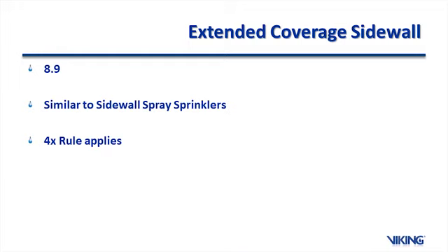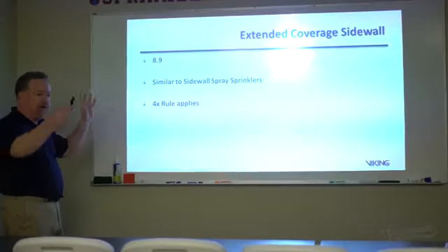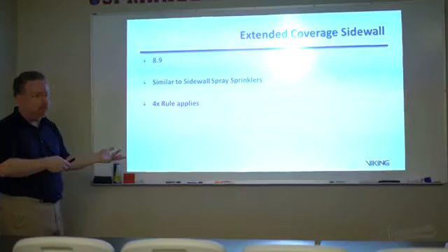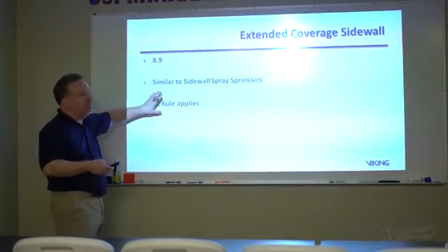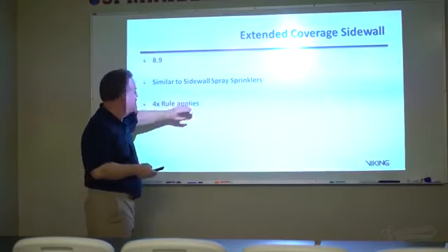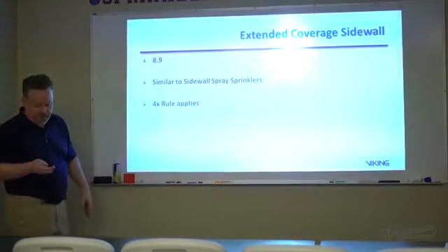Extended coverage sidewall is similar to sidewall spray sprinklers, except the 4 times rule applies. Okay, so if we went back to all those rules for the sidewalls, same thing applies, slightly different numbers and distances, but a 4 times rule instead of the 3 times rule.